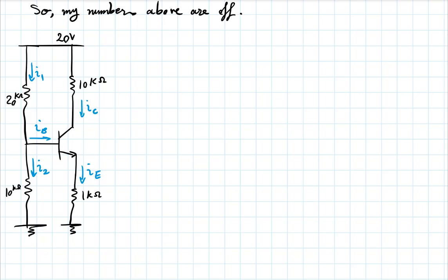Now I'm in saturation, and I know the things that I do know for this third attempt. Again, I'm applying some approximations here. Of course, you could do things much more accurately, but these are approximations that are qualitatively valid in this case. I'm in saturation. My VBE is approximately 0.7 volts.